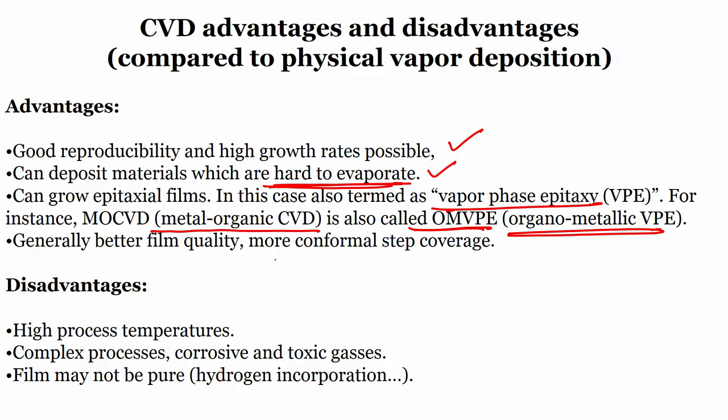Generally better film quality, more conformal step coverage. Step coverage is better in the case of CVD when we compare with respect to PVD, right. In the case of CVD, the step coverage is better compared to PVD.